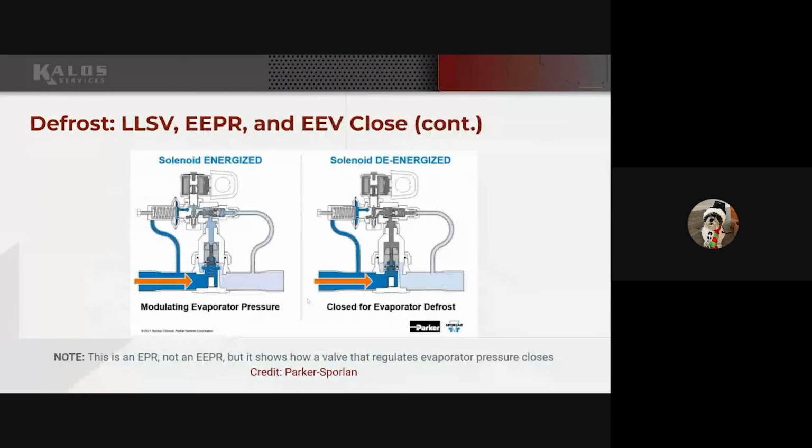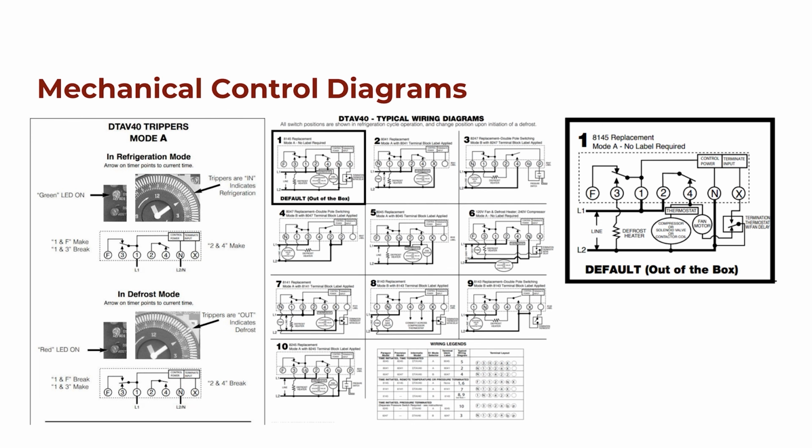Now with the compressor, there's still some control that's happening in this circuit, right? So we're just going to run power to our fans without any more control. As long as this time clock is closed, the fans are simply going to run. But this compressor, they're showing a thermostat in series with the compressor, in the case of a self-contained case.